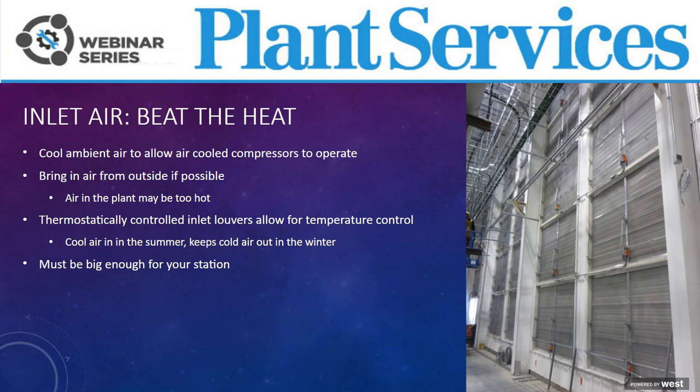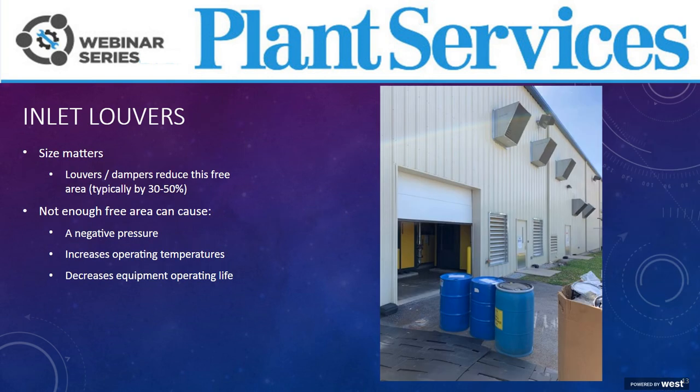However, one thing: installing a louver damper in an opening is going to reduce the free area of that opening. And this is true not only for thermostatically controlled units, but really any louver, damper, or bird screen. And keep in mind, even water-cooled compressors need fresh air. So let's talk a little bit more about those.